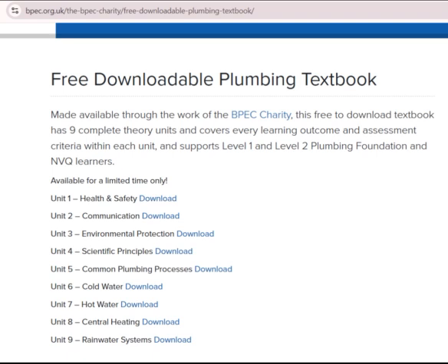AC 9.4. Identify the work sequences for permanently decommissioning central heating and pipework systems. Unlike temporary decommissioning, permanent decommissioning of a system literally means that the system will not be reinstated. In most instances, this will mean the complete removal of all pipework, components and appliances. The pipework should be cut back to the nearest live connection and capped to prevent stagnation of the water supply.